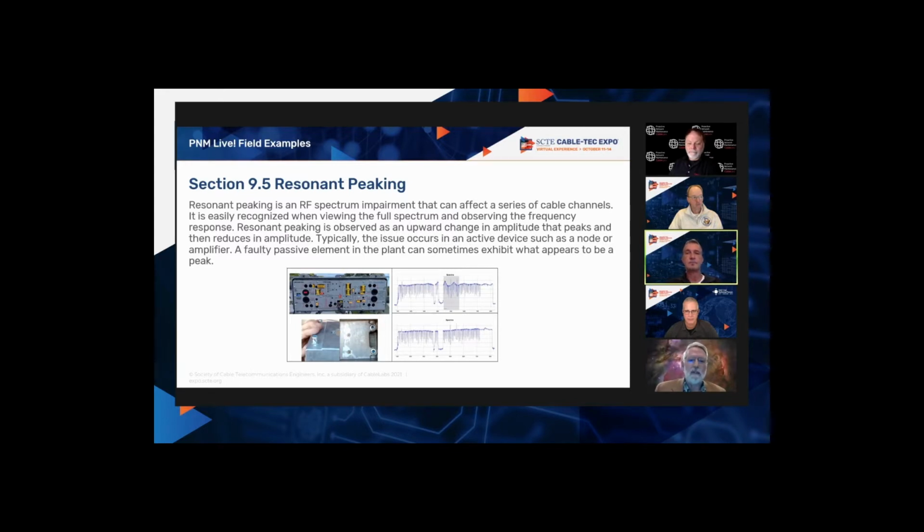A grounding issue inside the amplifier housing somewhere is causing RF feedback, and in this case, it results in an uncontrolled oscillation. The equivalent tone shows up as a spike in the levels of the RF signals, and you've got to deal with it the same way. We want to make that amplifier an amplifier, not an oscillator.